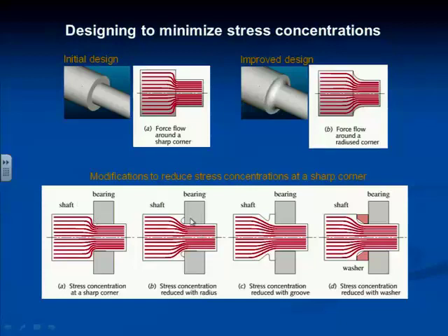For example, if I put a radius of this sort in there, this little nubbin here is doing the job of holding the bearing where I want it, and it has hardly any stress in it because the stress just went around the corner and down through there. Okay? In similar fashion, I could take it out of the backside, and I'm giving it a smoother path through, or I could add another part, which is essentially a washer, and I put a chamfer on the washer, and I put in the radius that I want, and that chamfer straddles the radius.